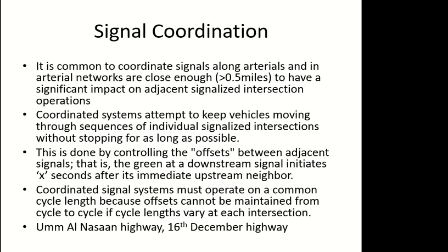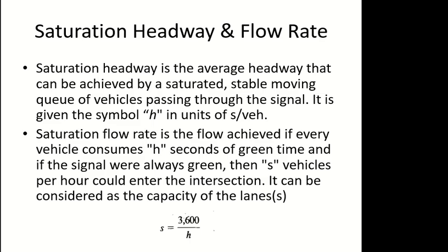But if you have a series of intersections close together, one direction has high volume and you want to facilitate that direction with signal coordination, you can achieve a non-stop flow for that direction, or a flow which is having a lesser number of stops. Okay, a couple of other concepts. The first concept is saturation headway, and then we have saturation flow rate as well.